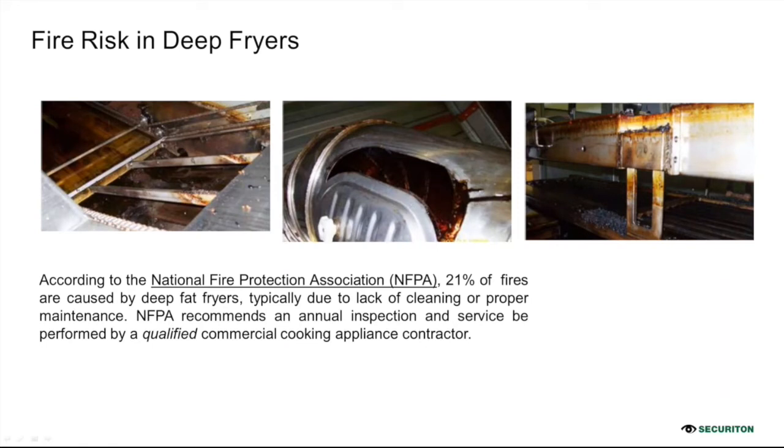This is because, as you can see in the picture, the fryer or the grease buildup could lead to intermittent operation or a failure of any detection system. When grease starts to build up in an existing probe system, usually sensor-based, it can lead to a false alarm. And a false alarm can lead to the wrong CO2 suppression system being triggered, unknowingly working in a wrong condition. This is also putting a risk and downtime on the operation itself.